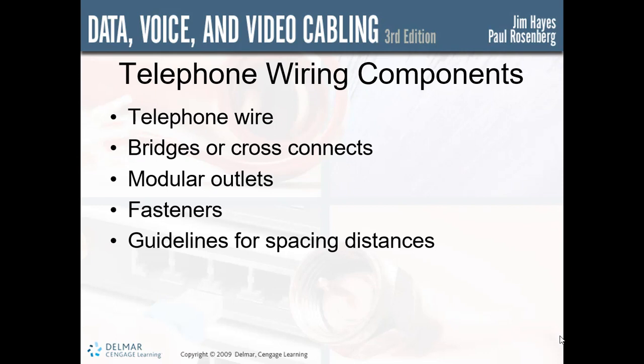And it must have at least 4 insulated conductor pairs, which may be colored green, red, black, and yellow, or may follow standard color coding, because a lot of times you end up with your 25 pairs, so you have different colors than what we're normally used to with our data cabling. The conductor should have an outer plastic coating protecting all conductors with a 1500 volt minimum breakdown rating.